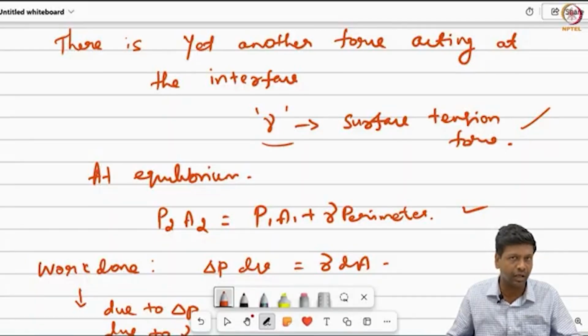Now, if you were to perform a simple force balance on these curvatures, or various geometries, you would understand that you also have to include gamma, along with the outside pressure acting on a given area, and the inside pressure acting on the area downward, and then you also have the surface tension force multiplied by the perimeter.